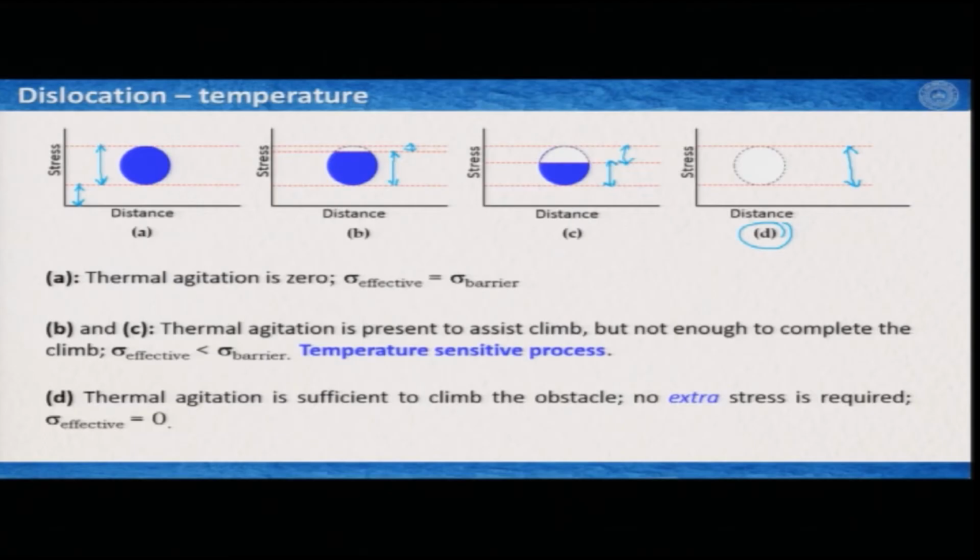So, at higher temperature you do not need much stress to deform the crystals. And if you remember, in our rheology lecture we learnt that at higher temperature the strength of the material decreases drastically, and now you know the micromechanics why. If you have temperature, then the crystals get enough energy to move the dislocations and deform the crystal through the process of intracrystalline plasticity.